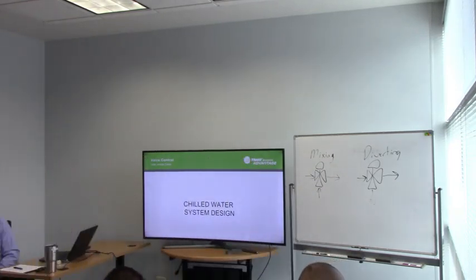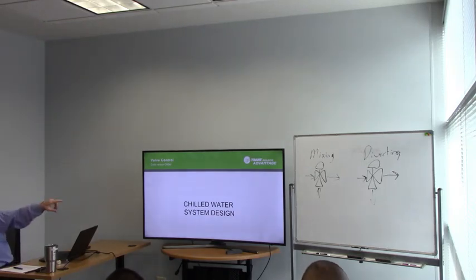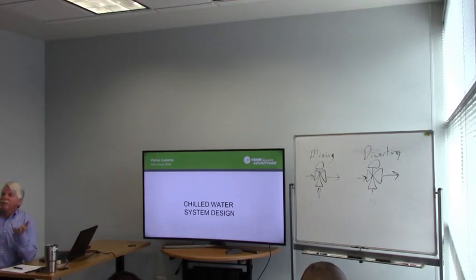And a long time ago, when they were manufacturing these three-way valves, it became a convention to use a mixing valve rather than a diverting valve. From a manufacturing standpoint, mixing valves were less expensive than diverting valves because they made more of them. And they have to be built differently, back in the days of globe valves. Now that we use ball valves on everything, it doesn't make any difference, same piece of hardware, okay?